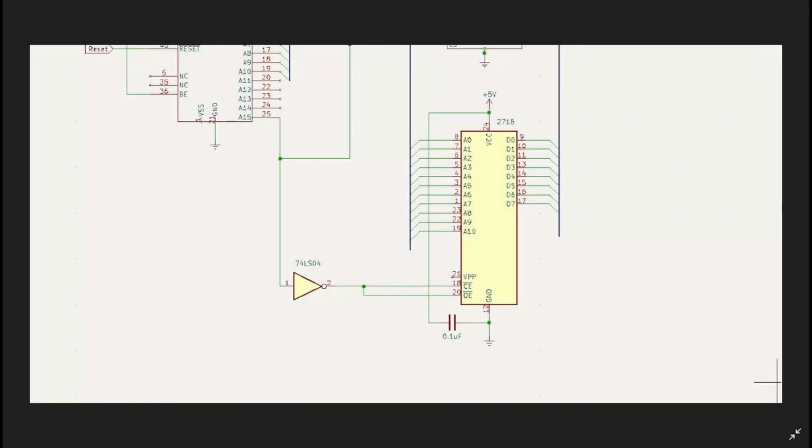Now, one thing that I didn't mention in the previous episode was that for these chips, we really do want to start implementing decoupling capacitors between the 5 volt and the ground rails. It takes away noise from the chips and makes them much more reliable. In this small circuit that we're using, it's not going to make a lot of difference, but I've already noticed on the larger circuit that without these decoupling capacitors, we really start to get ourselves into trouble.